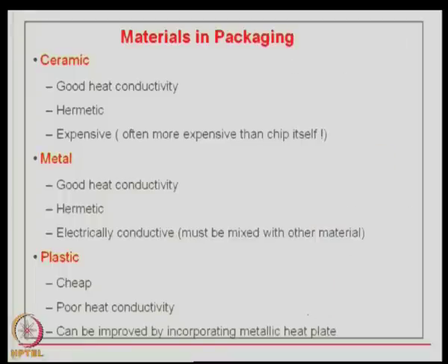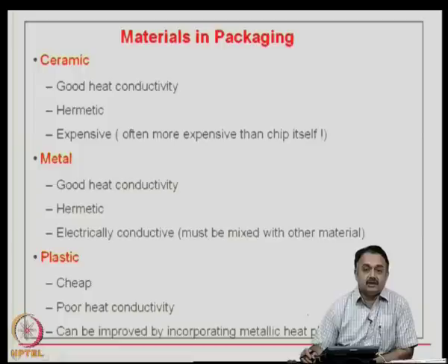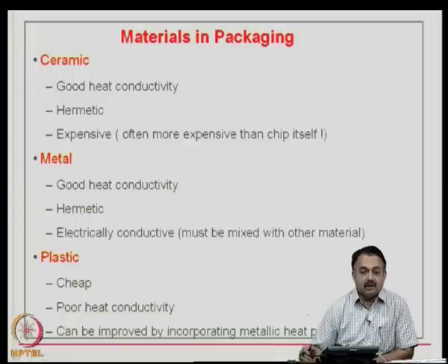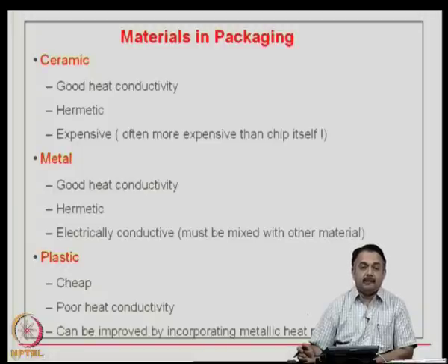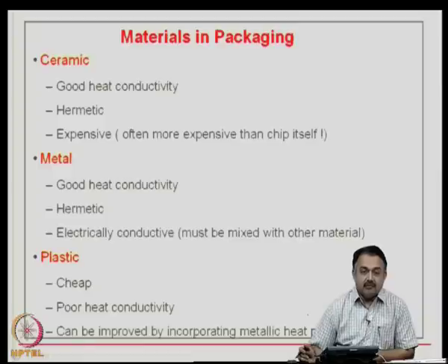Therefore, you can see now that materials in packaging are very important. The choice of a plastic package or a ceramic package is based on what you are expecting in terms of application. All applications need not have a ceramic choice and all applications need not be plastic. So, you have to carefully look at the circuit that you are working with, whether it is a power circuit, a communication circuit or an analog circuit, what kind of simulations you have done, and what kind of heat requirements there are in terms of material choice.